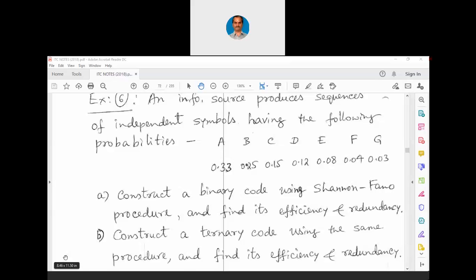Now, you may think that information is always transmitted in binary as 0 and 1, but fundamentally it is like that. But we can have different waveforms. For example, when you think about 0 and 1, you will think about 0 volts and, let us say, 1.8 volts. I'm giving a typical example of this VLSI lab where we are using the 180 nanometer technology, and there the VDD is 1.8 volts. So you may simply think that 0 is 0 volts and 1 is represented by 1.8 volts. That is for a normal standard binary communication.